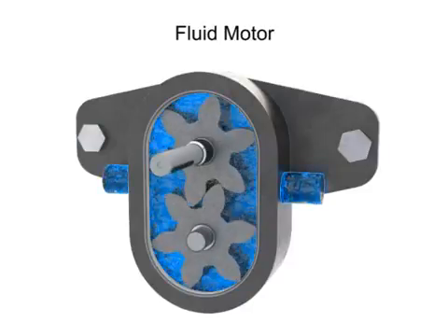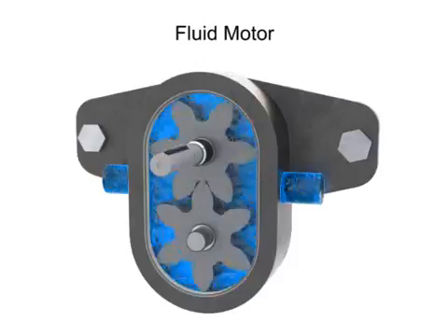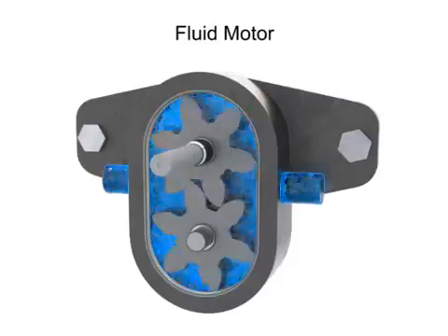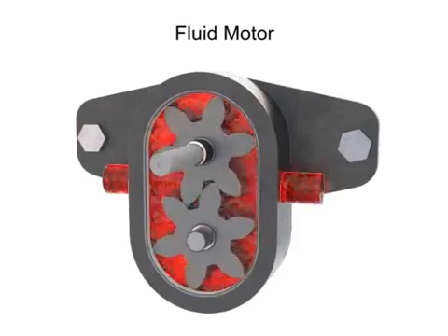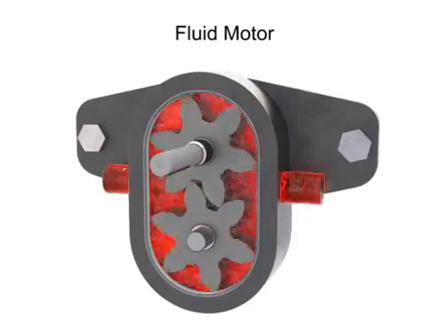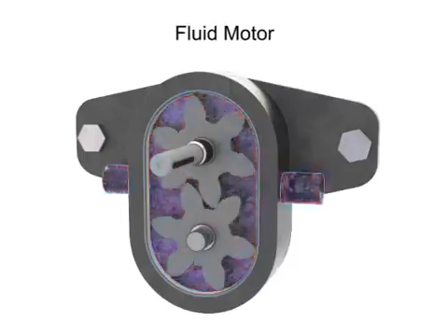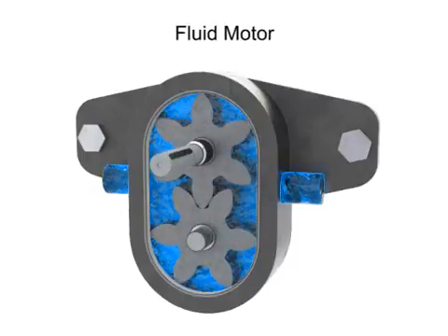Additionally, unlike an electrical motor, fluid motor speed can be made responsive to its fluid temperature. If a sensor detects an increase in fluid temperature, the speed of the motor can be directed to reduce. Due to their advantages, fluid motors can be the ideal choice for conveyors, hydraulic transmissions, fan drives, vehicle drives, cable reeling or winching, and many other industrial applications.